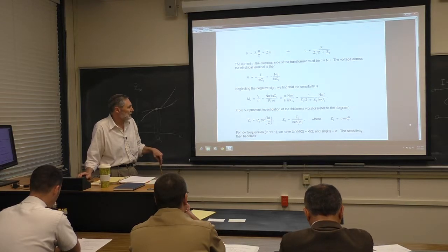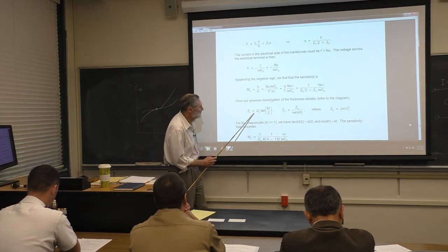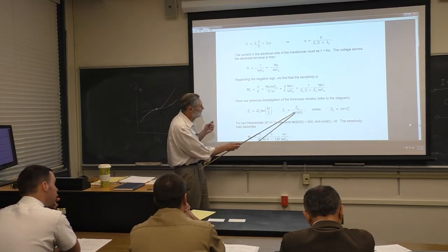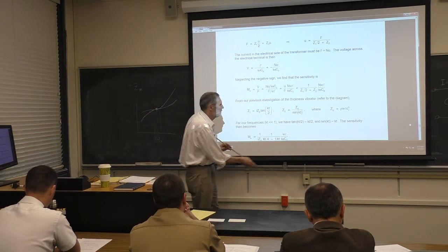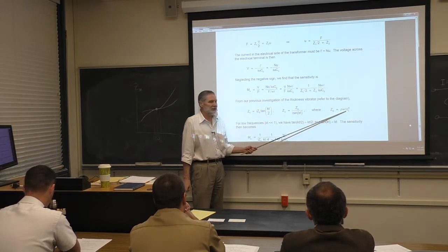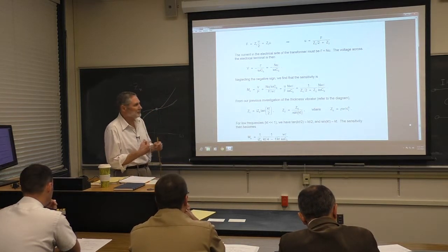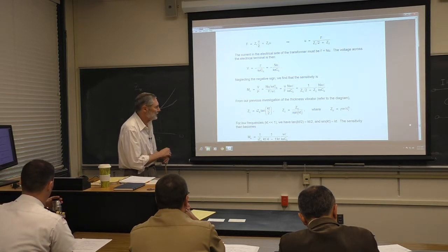Now, in terms of Z1 and Z2, and remember here Z1 and Z2, we've got the T's in there, that's good, they should be in there, it's thickness, where Z0 is equal to this. Remember this C here? It's not a stiffness, it's a speed of sound, the speed of waves, of longitudinal unidirectional compression and expansion waves.